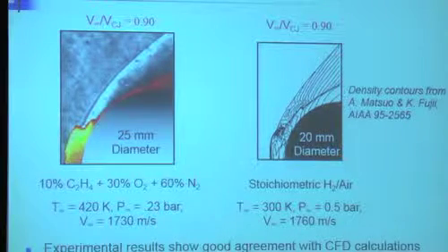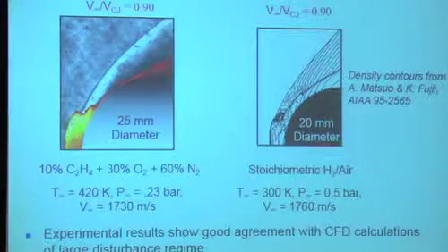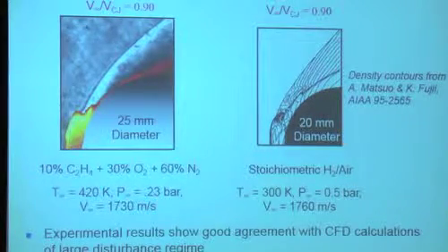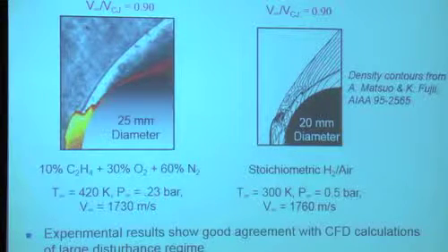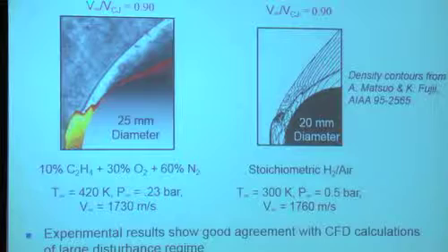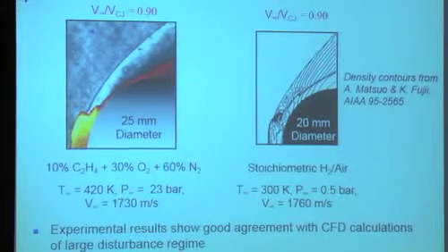So what's happening? We got into a regime where this is detonating, and that velocity was high enough for it to actually move forward into the supersonic stream and perturb this. That was the most interesting case of all. So when the free stream velocity coming in is less than the CJ speed, you can get into these regimes.